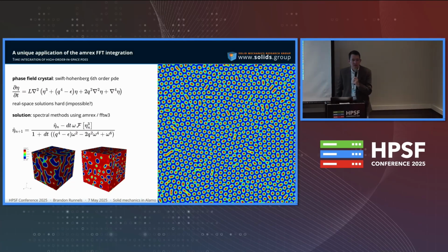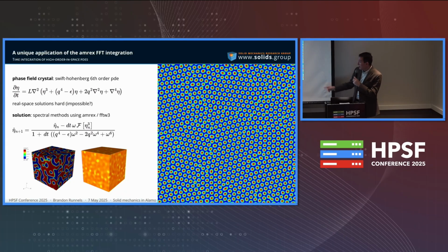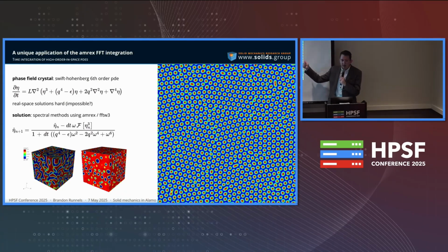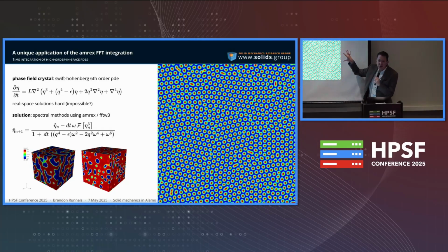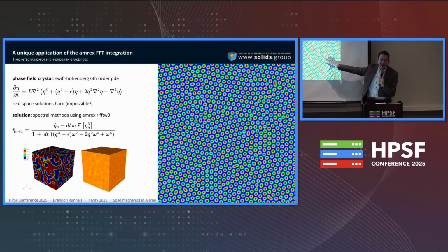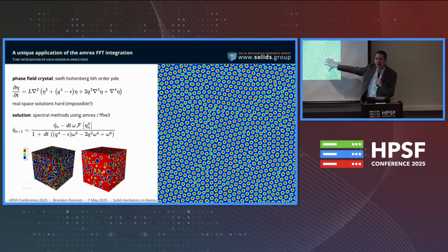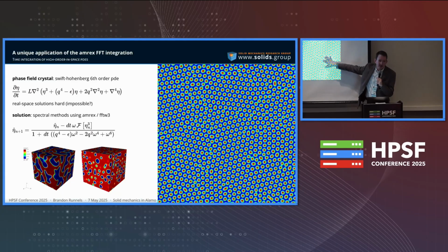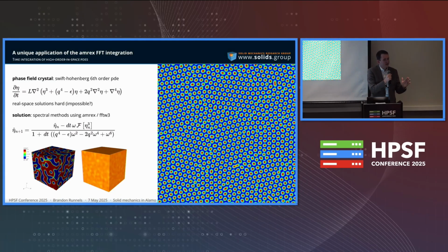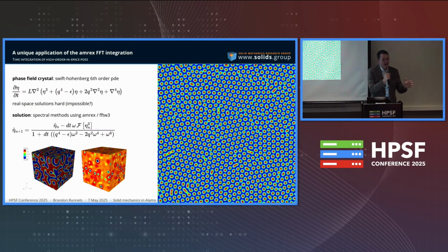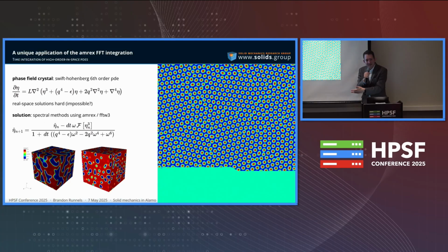But what is the fundamental difference between this and the other simulations that you performed? Yeah, well, if you look at this, there's absolutely no reason to use AMR on this simulation, right? You would instantly refine everywhere. So it's really kind of pointless to do AMR in a simulation like this. And so if your simulation doesn't really require AMR, then it's probably one that would do really well with an FFT-based solution, and vice versa.